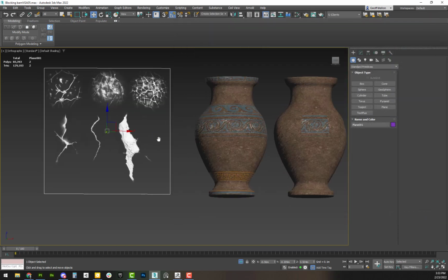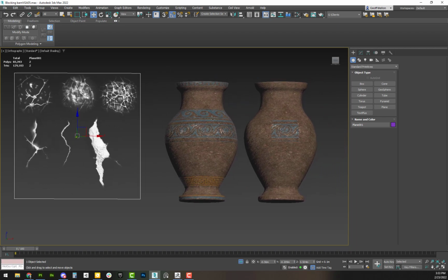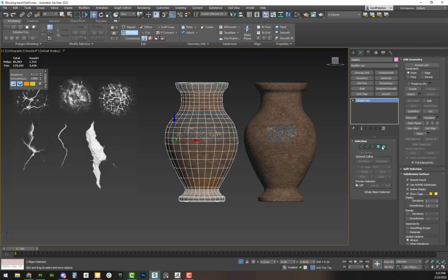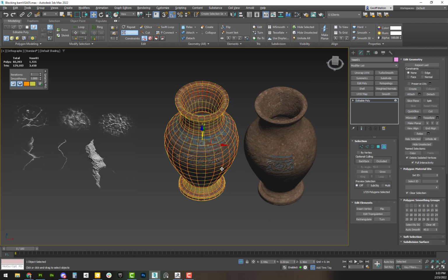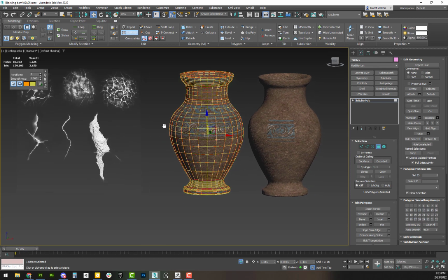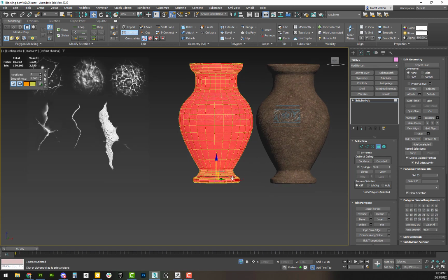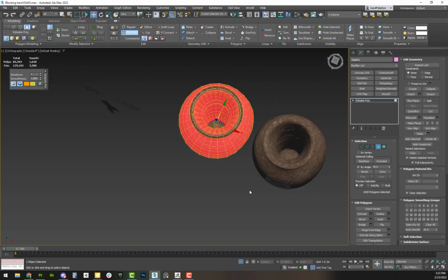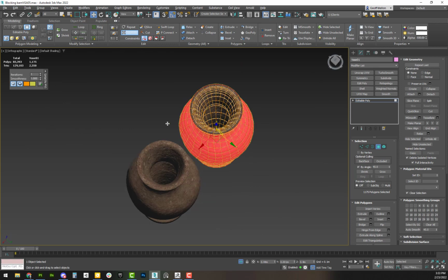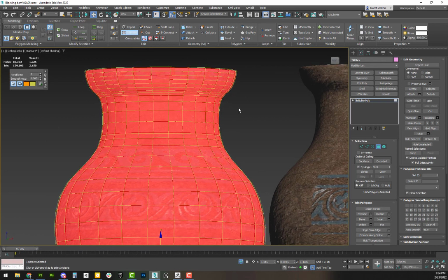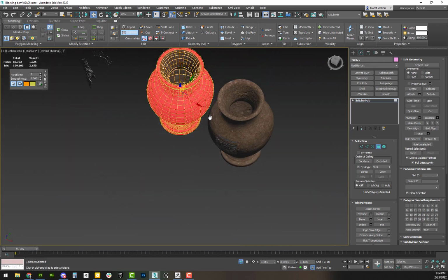And it's good to leave it white for right now because that way we can see what it's gonna do on here. So I'm gonna take this one, and there's a few ways you could do this. You could cut this up, do a bunch of stuff, but the way I'm gonna do it today is I'm just gonna grab the exterior of this face. I'm not worried about the interior. So I'm gonna go to by angle and grab it and hit F2 to make sure it's grabbing everything, and not this part, and maybe even this one. Okay, so I'm grabbing the whole base, the exterior.